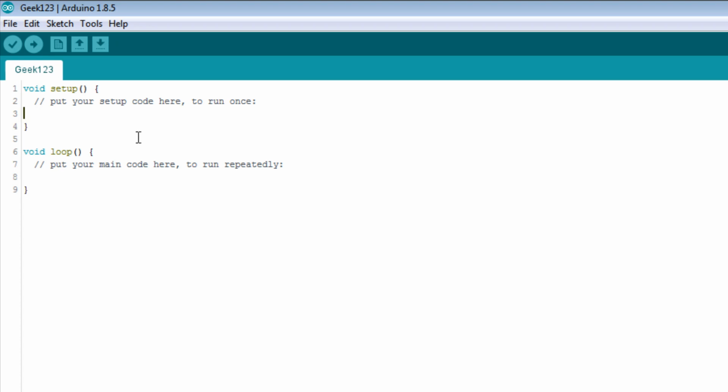Now, I'm going to make a change, and I'm going to write something. Let's see. Arduino rules. Spell that right. Now, you see, I made a change. You notice this little funky looking symbol, looks like two S's on top of each other, that appeared here. What this means is I made a change and the change has not been saved. So I made a change to the program, and I haven't saved it. When I hit save, it goes away. That's something to look out for, something that's good to know.